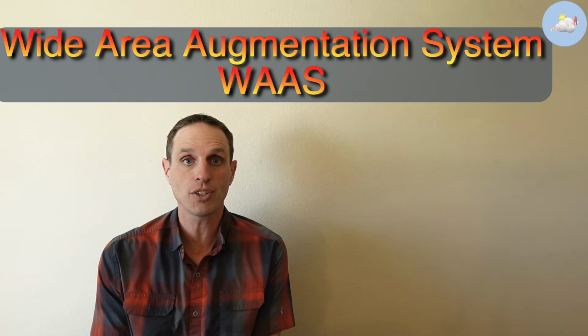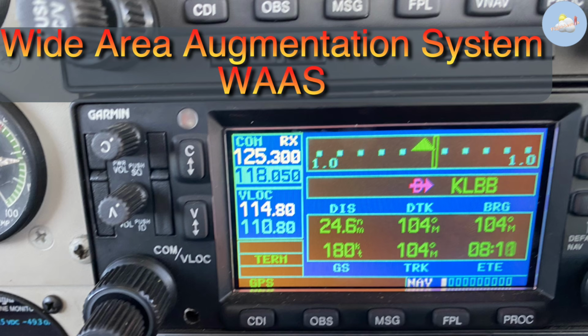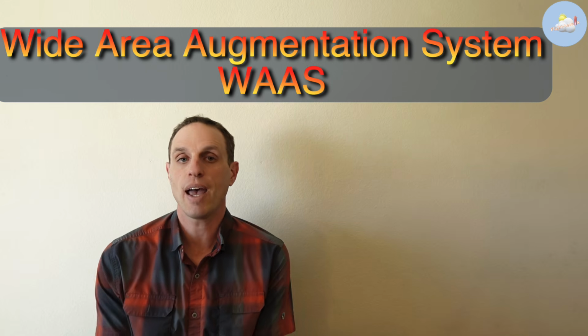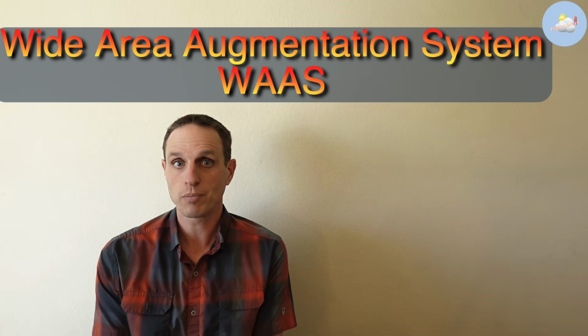height. Now, one of the requirements to have this advisory guidance on your GPS is you must have Wide Area Augmentation System, or WAAS. So early Garmin units such as the Garmin 430, 530 that don't have WAAS, and also some of the earlier G1000s without WAAS, are not capable of providing this advisory glide slope because you basically need to have an accurate altitude readout, which WAAS provides.